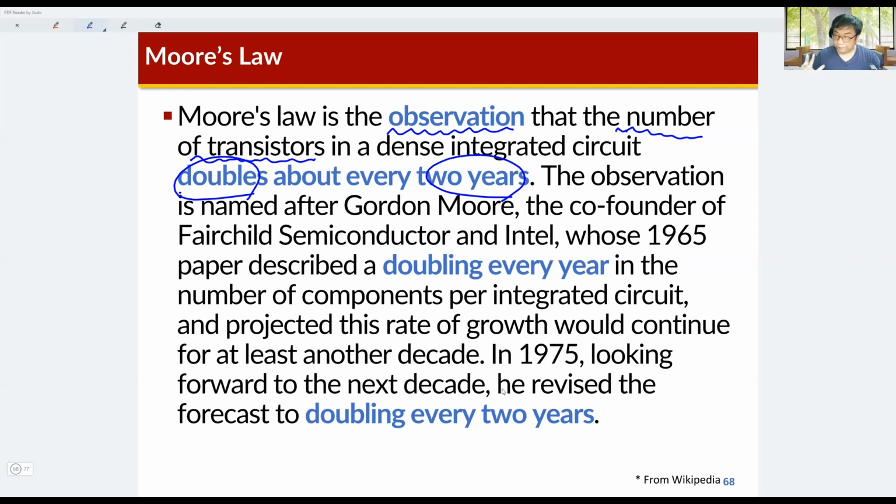Why? The channel length and the channel width are reduced. That means that the CMOS transistor can work faster. So the CMOS transistor works faster, so we can reduce the supply voltage, and then we can increase the clock frequency easily if we reduce the size of the transistor.